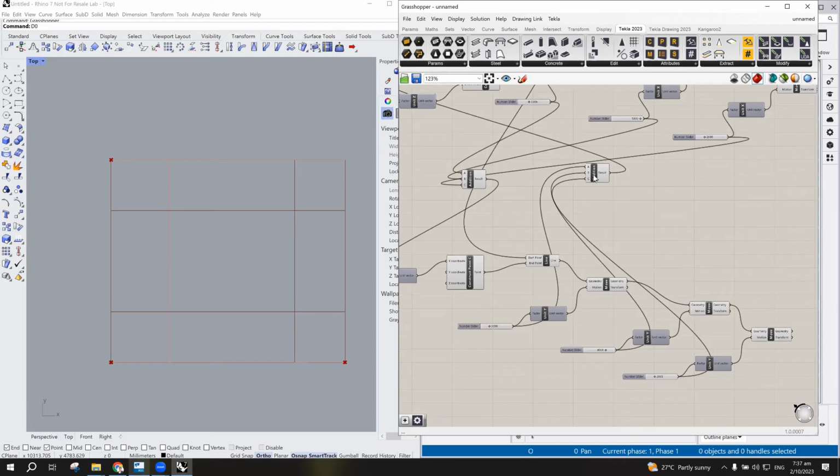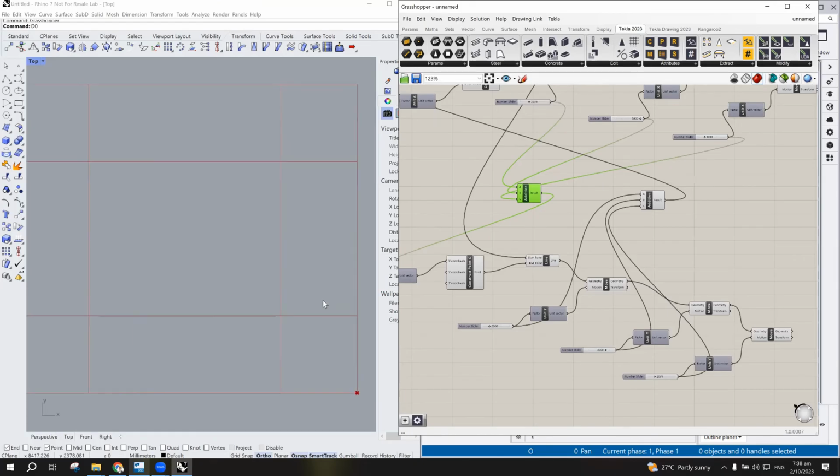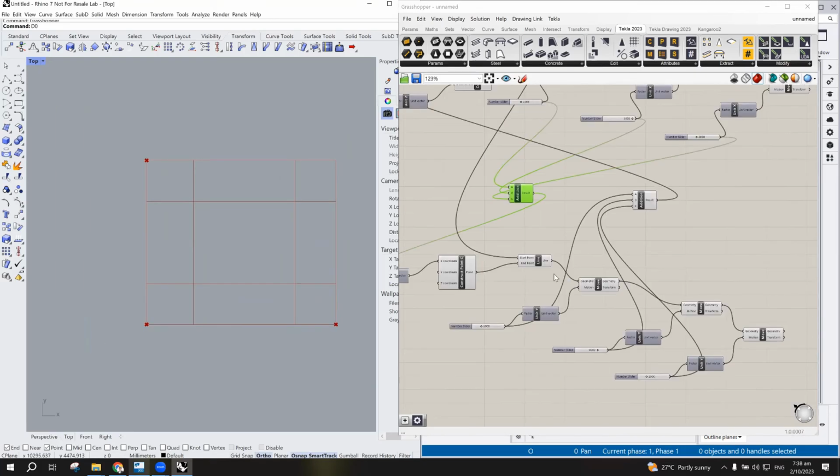Okay, you will notice that this one at the moment is a fixed one, fixed. So meaning the number, because what we are trying to do here is convert this one as a grid line in Tekla Structures. Okay, as a grid line. So if you notice here, it's more manual, but it's a fixed number of grids here because I have only 1, 2, 3, and 4.